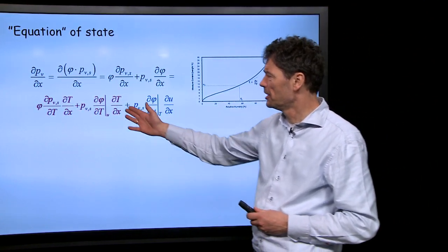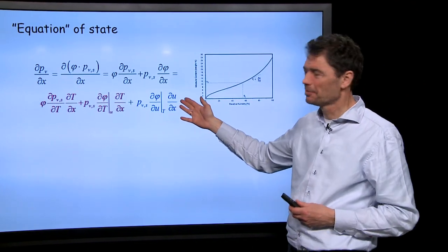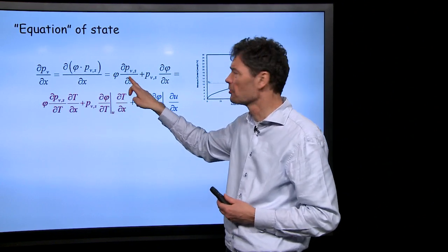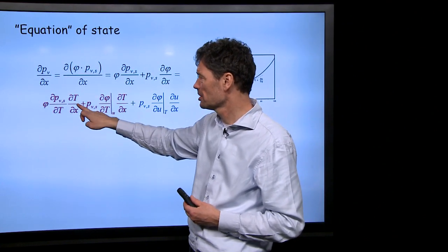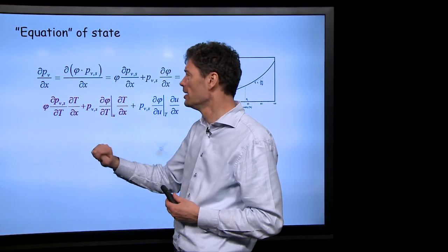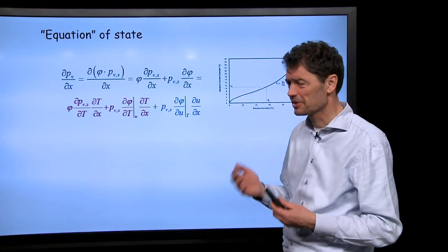Now it's plotted down here in red everything that is temperature dependent, and everything that's moisture dependent is in blue. And what is temperature dependent? That was how the saturation vapor pressure was temperature dependent. So we should consider dPv/dT, and then we can take the gradient of the temperature to give us that gradient.